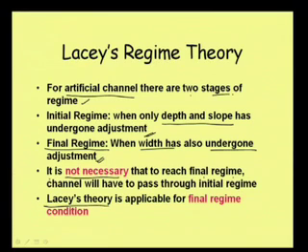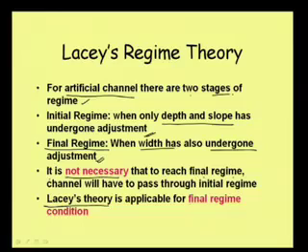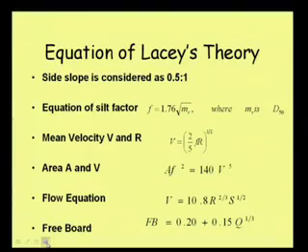And more importantly, Lacey's theory, what he studied, and the formulas he has given based on his study, are applicable for the final regime condition. So once we are designing a channel, we should know that we are basically designing considering that this is the final regime size, and so those formulas will give us this value. Well, then he gave a series of formulas.